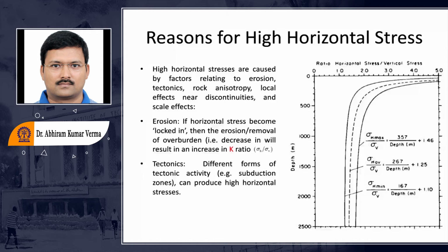One more topic is there, called stresses around underground openings, and how we can control the stresses on any structure or any underground excavation to increase their factor of safety without adding any support or any sort of investment. Only the reorientation of the direction of your openings is going to solve your problem.